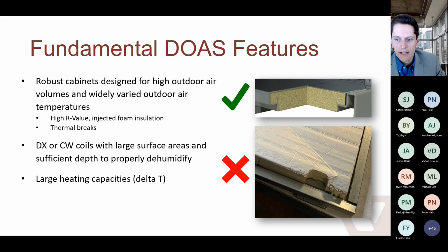And then your heating components, similarly, dealing with very low temperatures and large delta Ts, those need to be sized appropriately for a large capacity electric heater, for example, or furnace. And then also modulation is important. Remember, we talked about modulating those components to meet those part load days. So high turn down is really important.